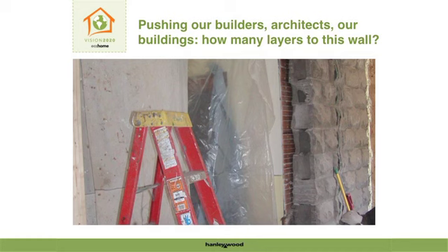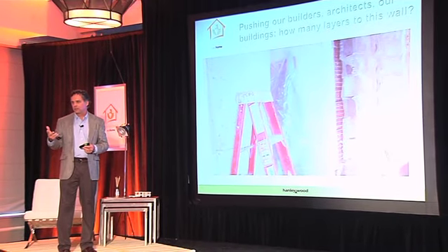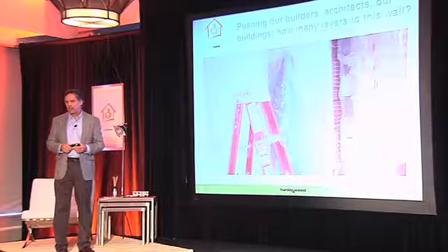An awful lot of my time is taking a look at the science of the building enclosure. And in older walls, the physics was pretty simple, straightforward, with simple, robust products. This is my house built in 1911, and this is part of the retrofit we were doing to expand the kitchen. But how many layers does that wall have over on the right-hand side? 3. Concrete block, wood lathing, and plaster. It's pretty easy to get the physics of that right. And there's only really 3 things that we're asking of that wall: structure, finish, and management of bulk water.